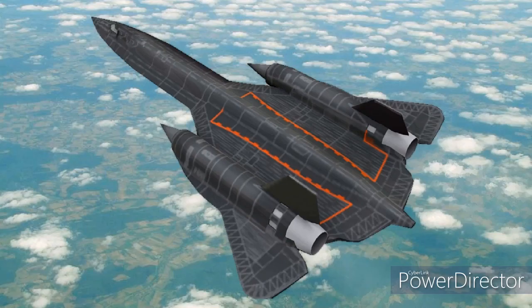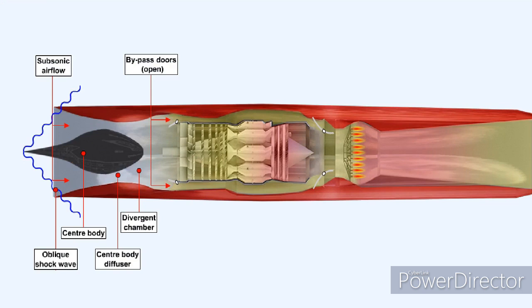The Pratt & Whitney J58 engines fitted to the SR-71 were unable, at high Mach numbers, to carry the large mass of air entering their inlets without stalling their engine compressor blades. At these speeds, the excess air was directed through a bypass system straight to an afterburner. This effectively converted the engine from a conventional turbojet to a ramjet in flight.